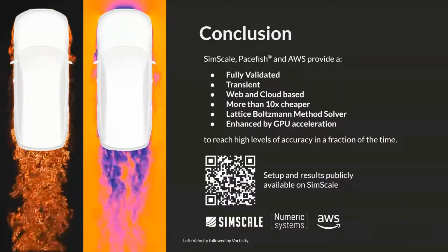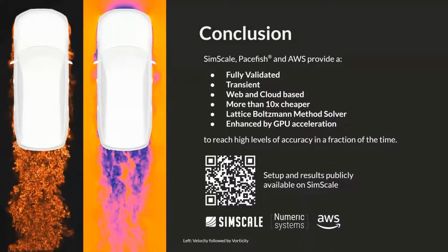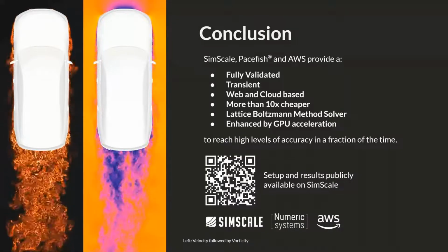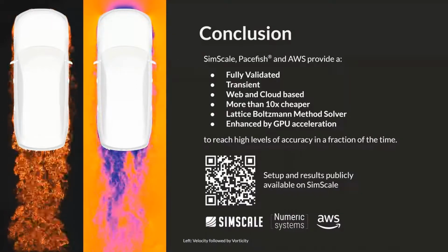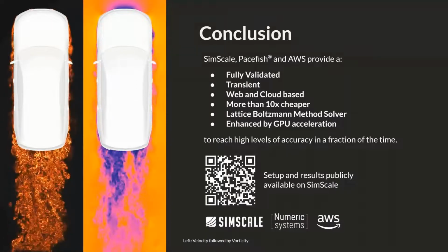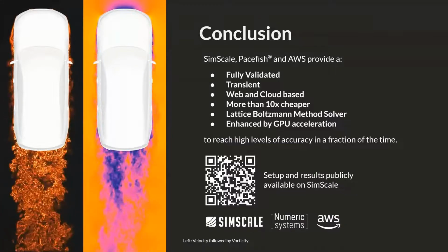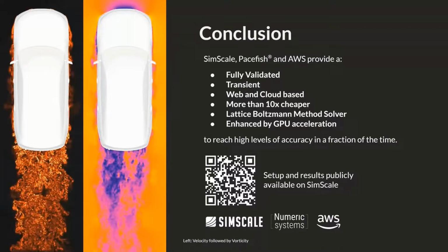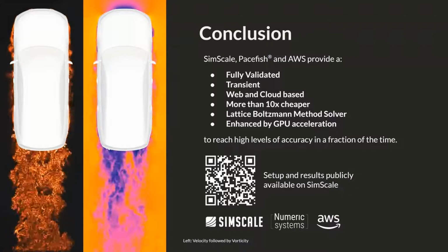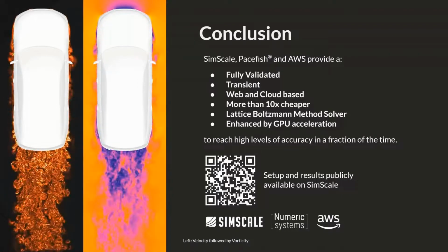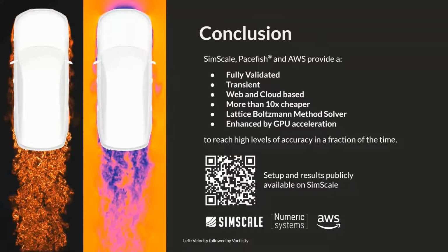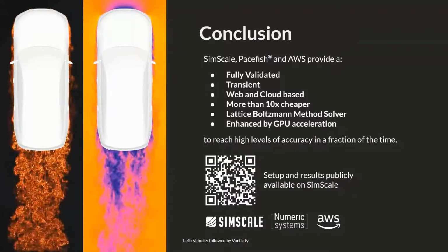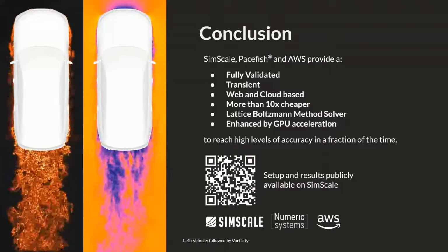Current automotive workflows then take several days to mesh, ensuring cells are within mesh quality metrics and resolved to a specific level in specific regions, and can take many man-hours in multiple days. SimScale renders this unnecessary, as LBM lattices require cell aspect ratios of 1. The Pacefish meshing algorithm is robust and tuned for automotive applications, resolving detail where it needs to be resolved. Fully automatic meshing settings were used for all DrivAer models.